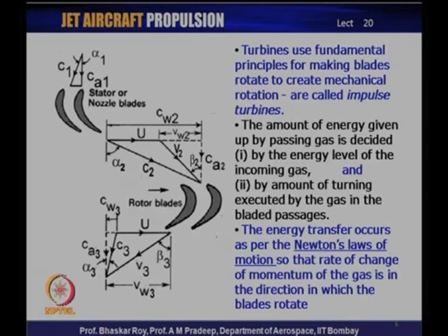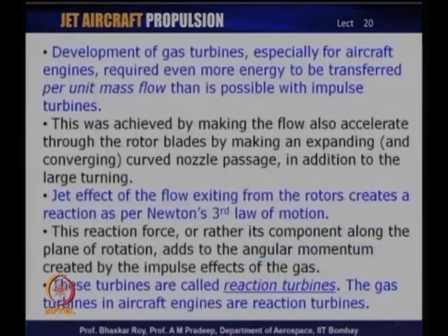We shall see very soon that, just as you had seen in the case of the compressor, these whirl components Cw2, Cw3 and indeed Vw2 and Vw3 have a crucial role to play in quantifying the amount of work that is being done by this rotor, and we shall write them down in a few minutes from now.